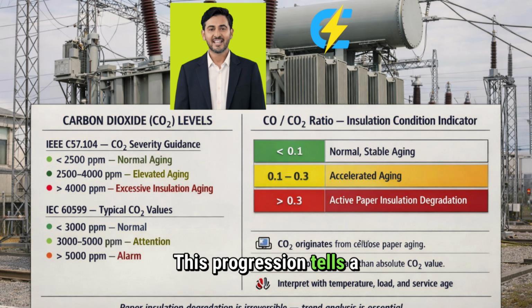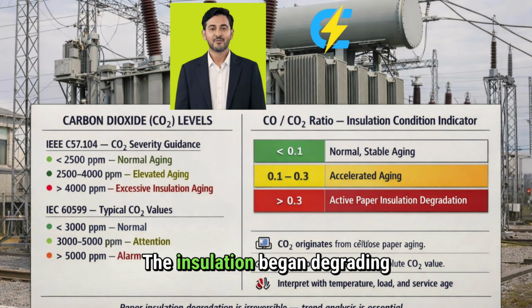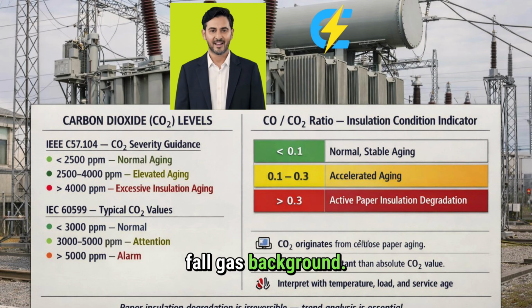Maybe loading increased, cooling became less effective, or moisture entered the system. The insulation began degrading more rapidly, producing more CO relative to carbon dioxide. But here's the crucial engineering principle. Never interpret carbon dioxide to CO ratio without considering transformer age, loading history, oil temperature, and fault gas background.